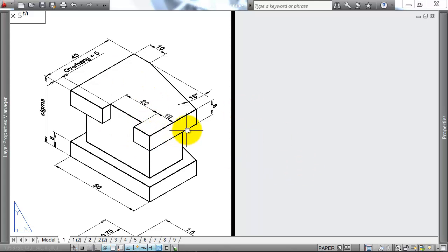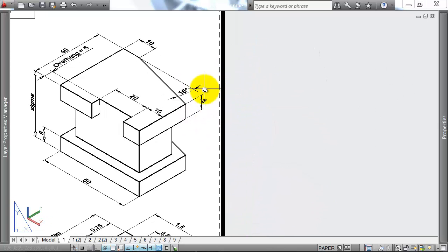So let's start with this one, and I'm going to try and take up just as much space as I've got over here so that I can keep the view roughly the same. What do we need first? We've got a line over here at 40 in the top view. So the top view is going to have this part of the shape 40 units long and this part of the shape down here 50 units long. So I'm going to shrink that. My scale factor is going to be a half in this case because I don't want to take up all the space over here. So I need to go down 40 on 2, so 20 units, and instead of going across 50 I'm going to go across half that, for 25. The first thing I'm going to do is just make a box that the shape is going to go inside.